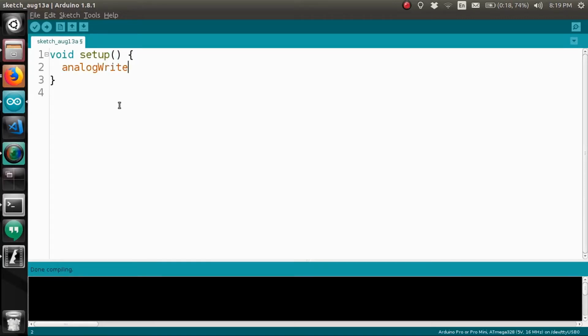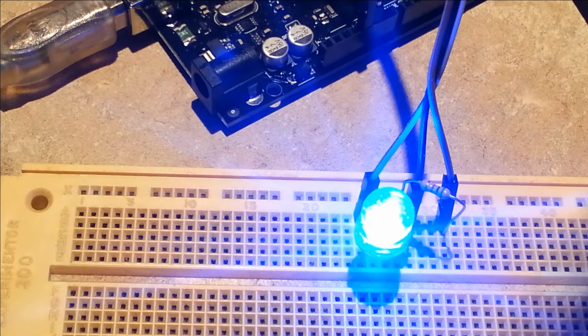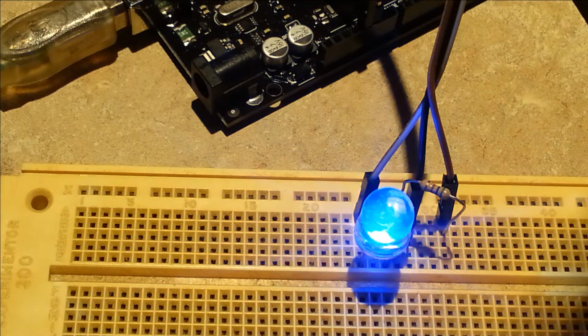Consider analogWrite, the function for controlling pulse width modulation. Once it is executed, the selected pin will continue to toggle at the desired duty cycle while the rest of the program moves on. Have you ever stopped to think, I wonder how exactly the microcontroller produces the correct PWM signal in the background without any sort of loop? Would you be surprised to find the answer involves triangle waves?